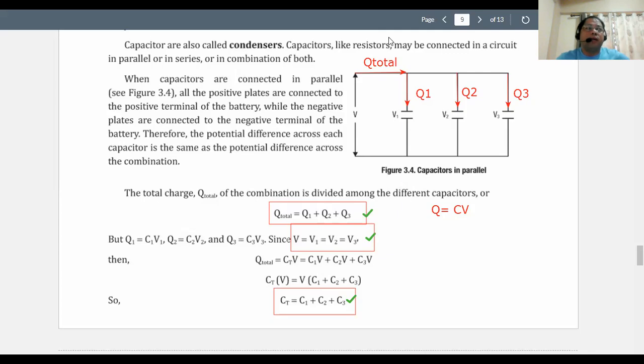Now, if you try to buy equipment that is only 110 volts, never attempt to plug it in the outlet, because the outlet in your house is 220 volts. If you bought that equipment outside of the Philippines, most likely it has a different voltage. If it's not auto-volt, meaning it will not automatically adjust its input voltage, never plug it in your outlet because the equipment will simply be damaged. This is how we reason out that voltages are equal whenever we have a parallel connection.